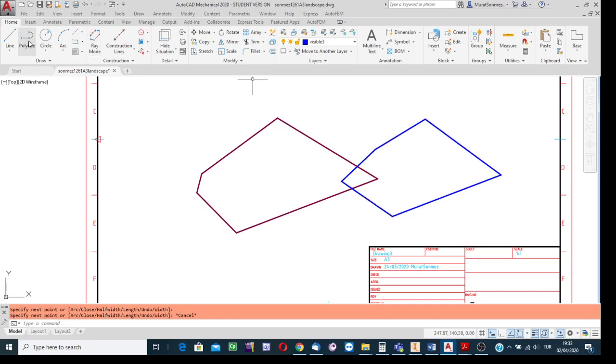If you create the straight lines using the polyline facility, then in the end, after having a closed boundary, the area bounded by the lines will be a region. And the lines will not be independent from each other, but in sequence, in continuation, forming the same boundary for the region. Okay, the first case I think is okay. In this case, we know the length of the line and we know the inclination angle.